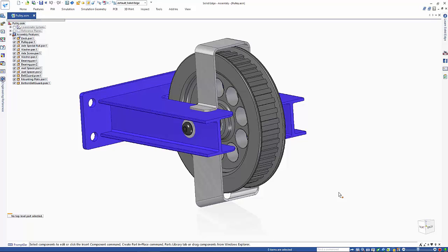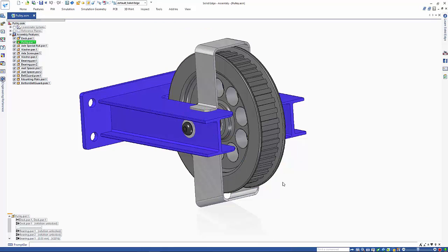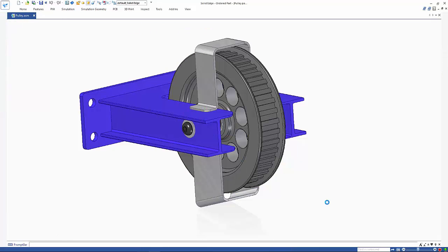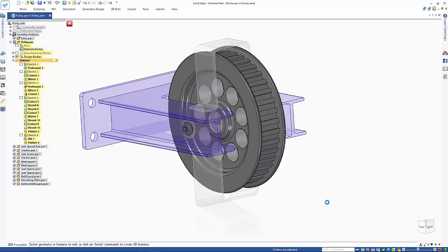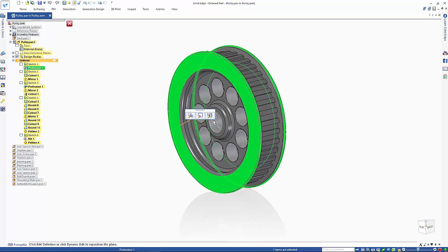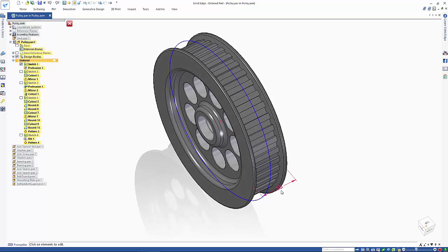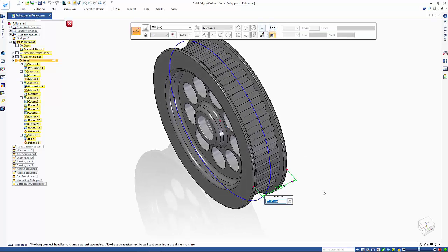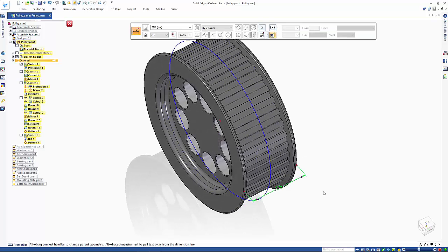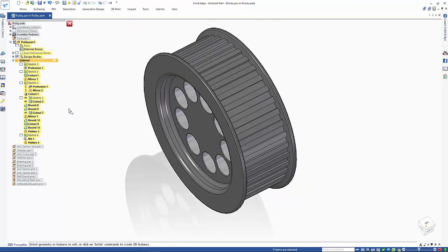First of all, let's approach this as you would in most any other CAD system using history-based editing. After we in-place activate into the part file, you will notice the list of the features on the left. Since I need to make the pulley wider, we can easily select the side of the pulley to make the initial edit. We see there is an overall dimension of 35, which I can change to 55. That makes this easy, or does it?